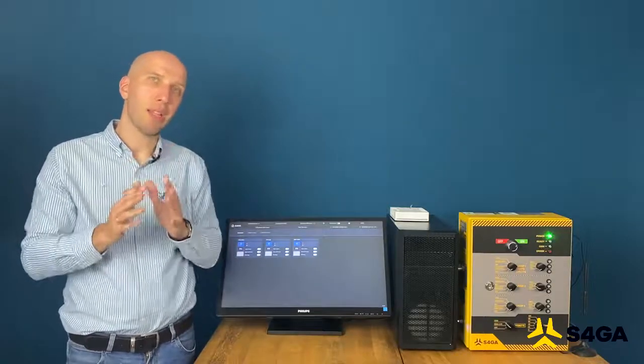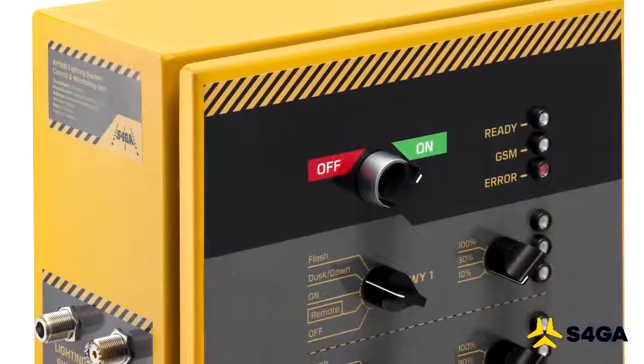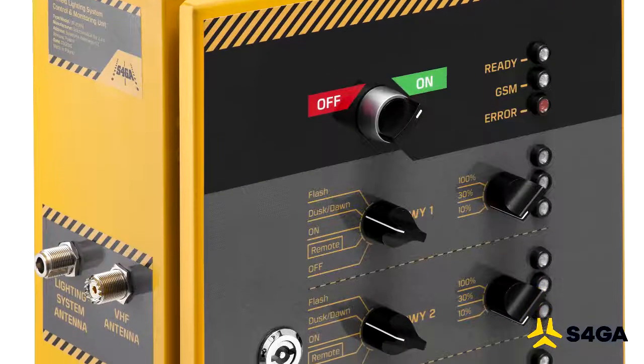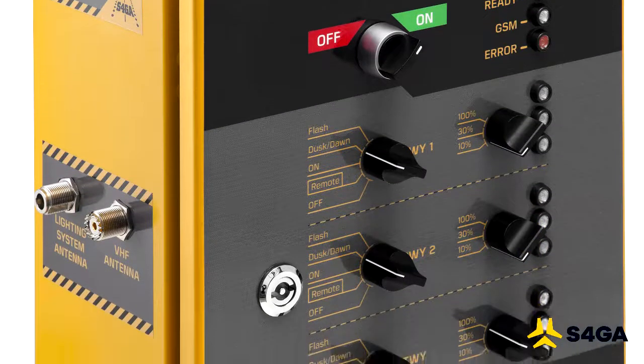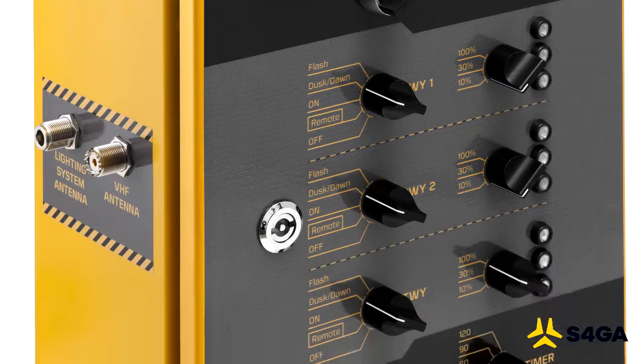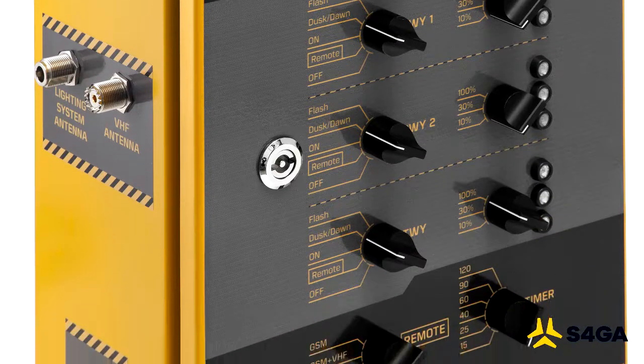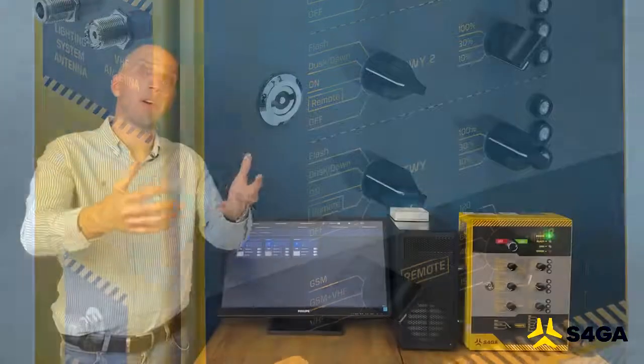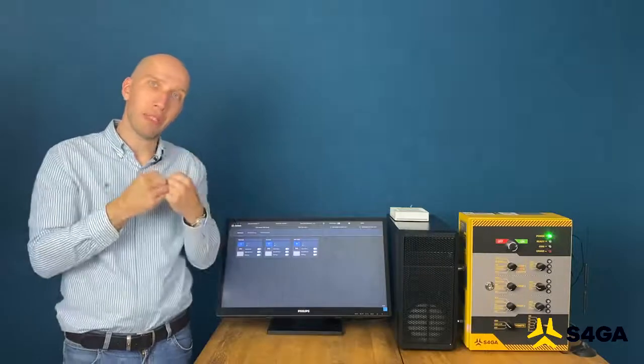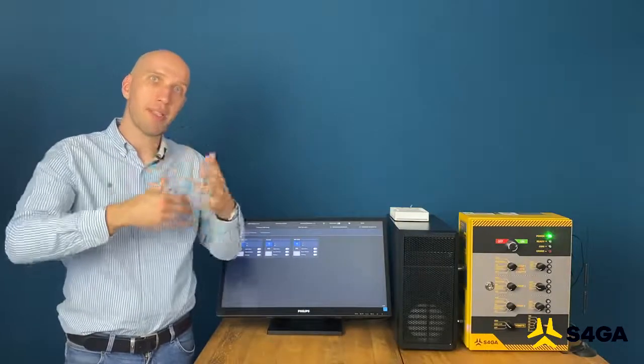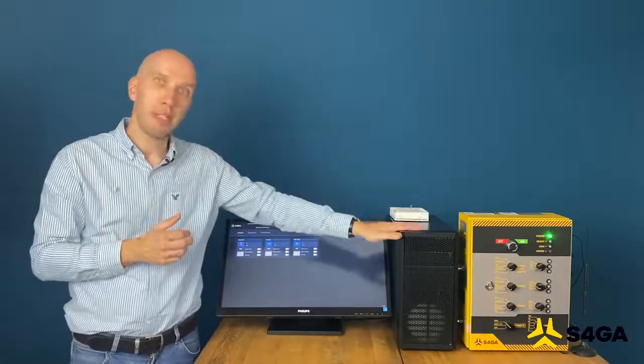The UR201 control and monitoring unit is an essential element of the whole setup. It is responsible for establishing connection between ALCMS and the lights on the runway. It sends the commands, it controls the lights, and also it collects the data from the lights. It transmits this data to the PC.